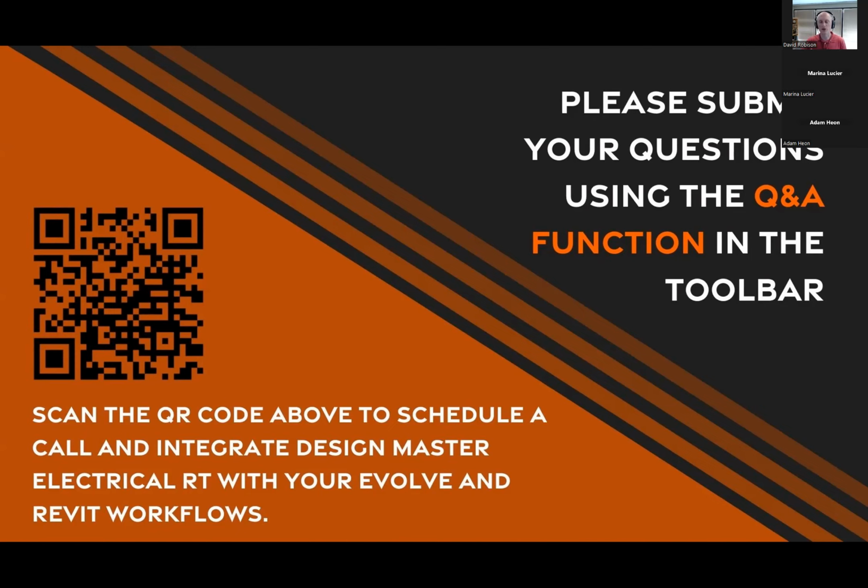And so if there's any elevation change, we'll see that. We've got the wire makeup that's just additional length added. So if it's in a tall ceiling, if you want to add 20 feet, you can do that. And then it'll update. So we've got all those options there for calculating the length. So there's a lot of different options. And again, these are engineering lengths. These are not Evolve lengths. They're not contractor lengths.